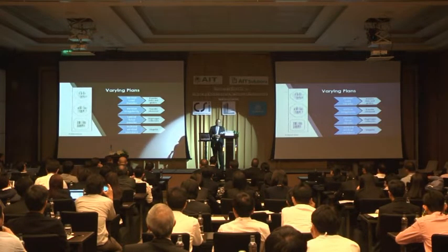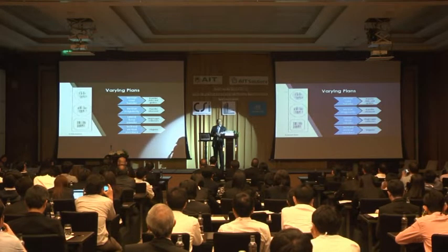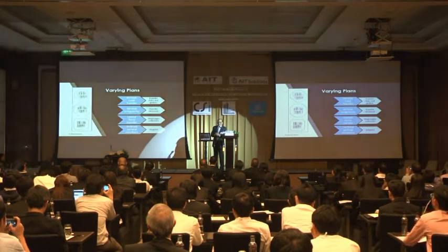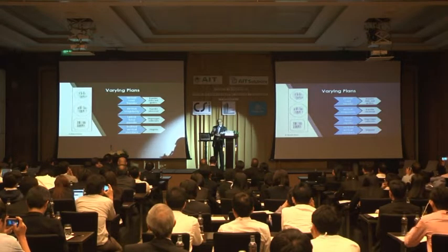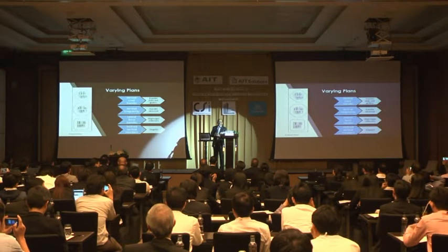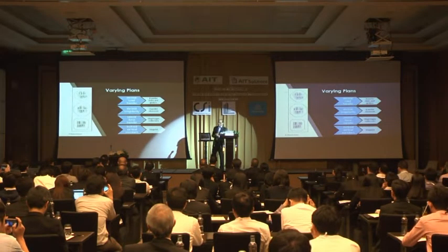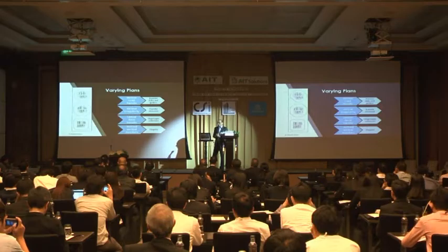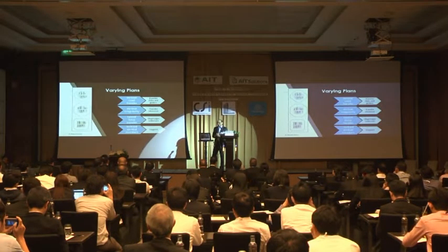Varying plans, plan changes along the height. This is very fashionable. I will show you some examples later. And if that happens because of a twisting building or just the plan being changed for use, then we get into vertical load transfer irregularities, lateral force transfer problems, inclined vertical members.